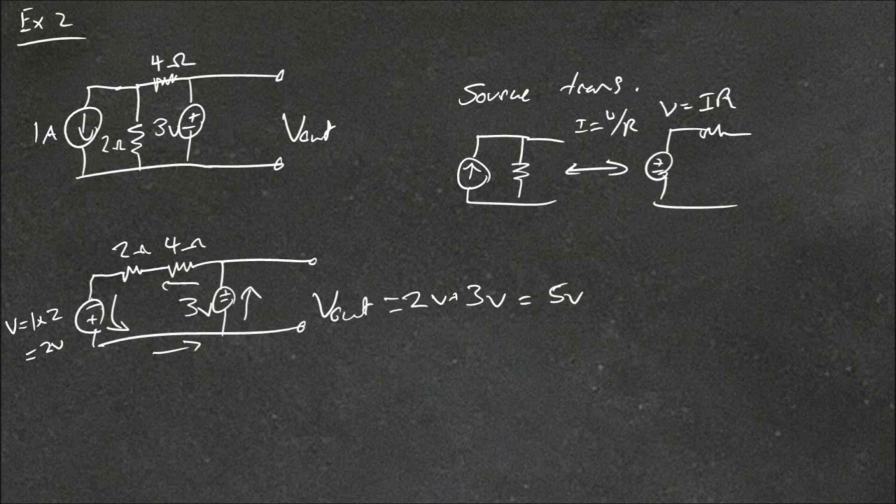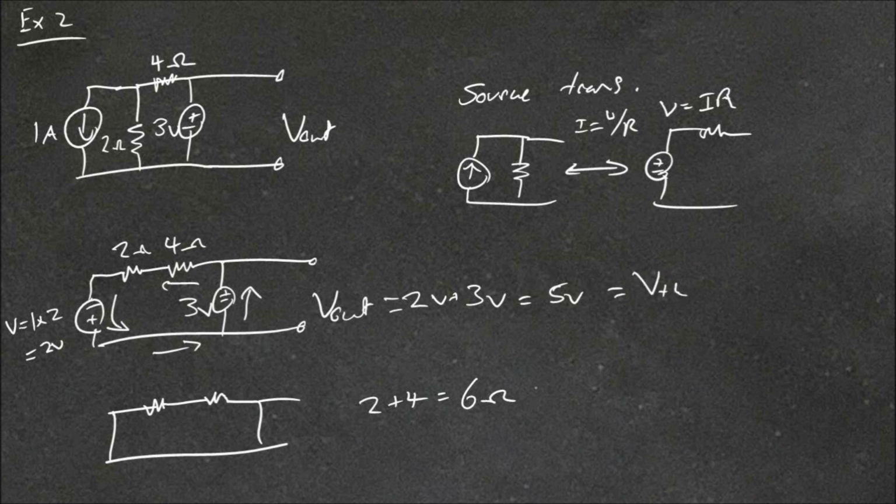To find the resistance, we short circuit our 2 voltage sources. So that's just short circuit, a resistor, our other resistor, short circuit. And these two are in series, so it's just simply 2 plus 4 equals 6 ohms. This is our Thevenin, and this is our Thevenin.